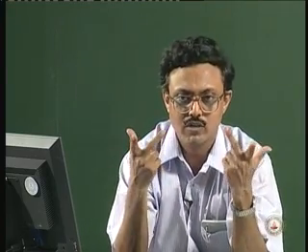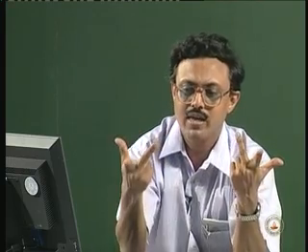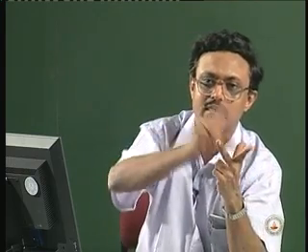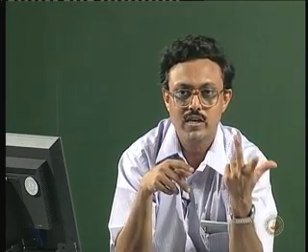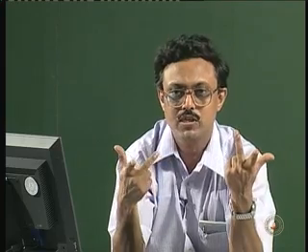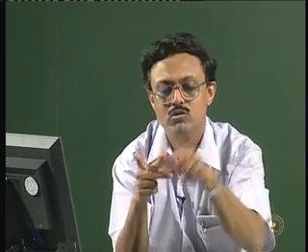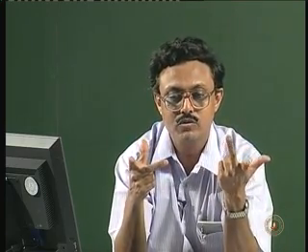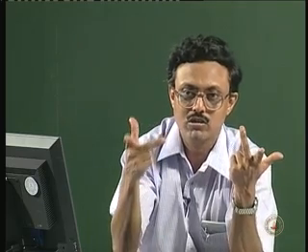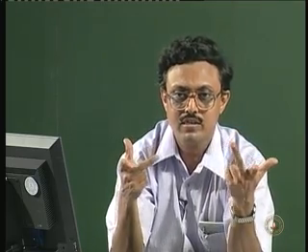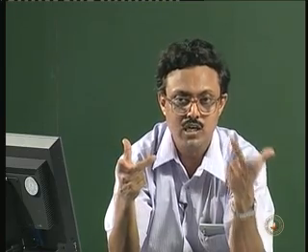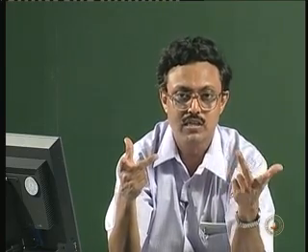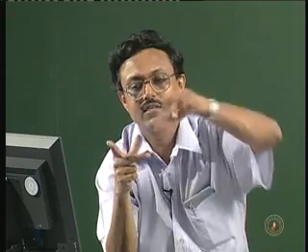Of course, we are talking of Cartesian coordinate systems x, y, z and n, u, v, let us say, and you want to put this here or you want to put that here. You can do that very simply if you know the corresponding unit vectors of the other axes with respect to the one which you are mapping onto or aligning it with. If you know these vectors with respect to this coordinate system, let us say the source and the target, then you just form the transformation matrix with the help of these vectors, put the coefficients as these unit vectors, apply that, and the system gets aligned.